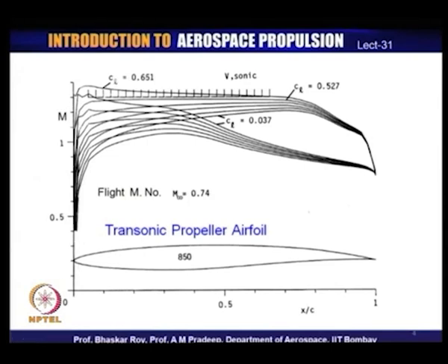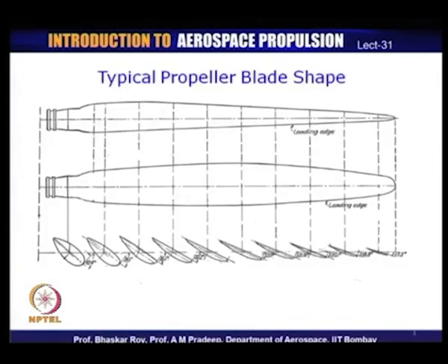So, this is a typical transonic aerofoil shape, and as we have seen, you need more of these aerofoil shapes to make up an aerofoil, a propeller or part of a propeller. Most of these aerofoil shapes are computer generated by the designers and then blended into a propeller blade shape. A modern propeller would have transonic blade shapes around here, but it would still have subsonic blade shapes in the lower half of the propeller, and they would continue to look something like this.